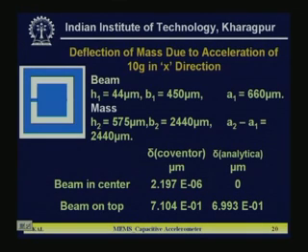So, that is why it is 0, but some movement along z will be there if you put x direction acceleration. So, that is why in Coventor accept that. There you are getting some value which is very small. Delta is the displacement along deflection of the mass due to acceleration 10G in x direction, that is the delta here.